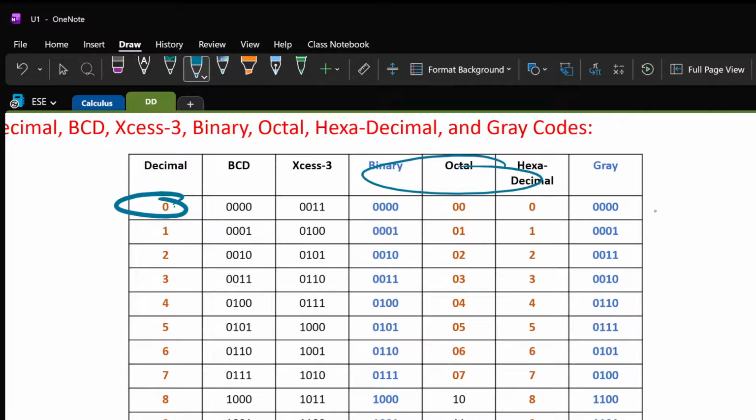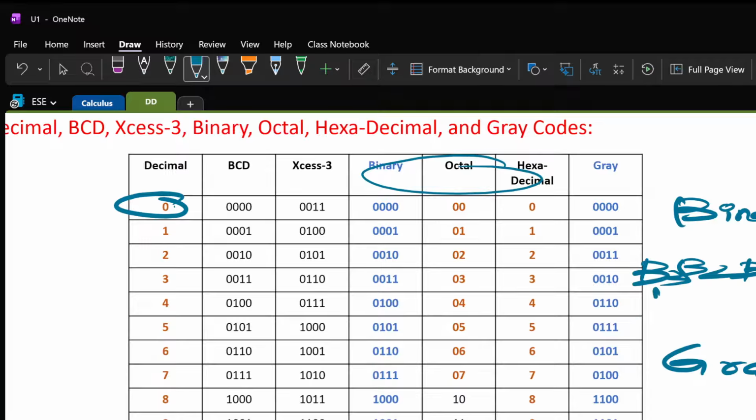Now, how do we deduce this? Whenever you have a binary number, you want to convert that binary number to gray. Let's call the binary number some random 4 bits, B0, B1, B2, B3. To convert this to gray code, you will copy the exact MSB position as it is, so B3 will just become G3. And then you will compare B3 and B2. You will see if B3 and B2 are going to be the same.